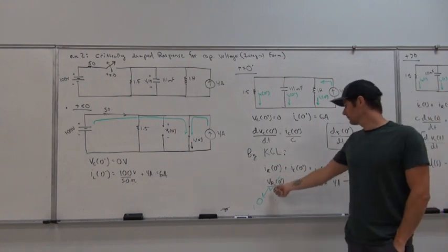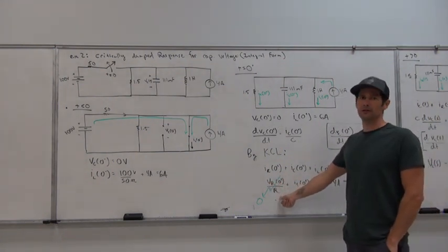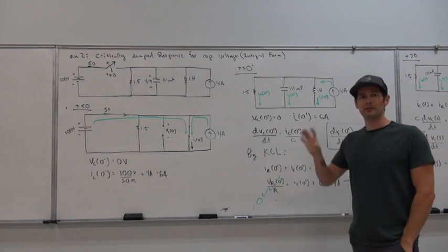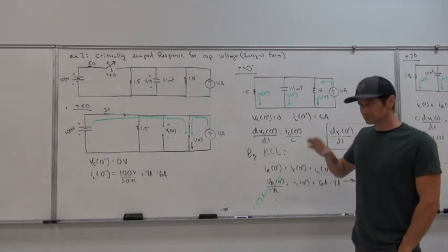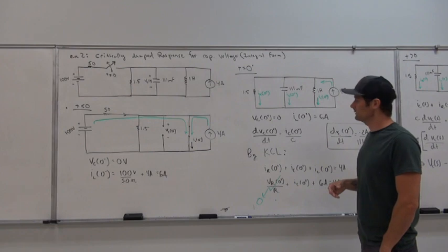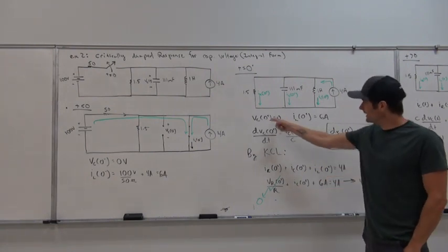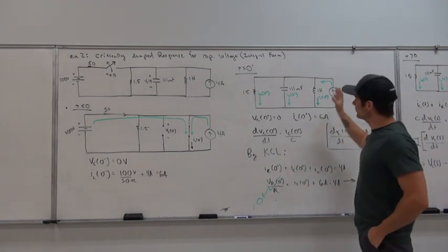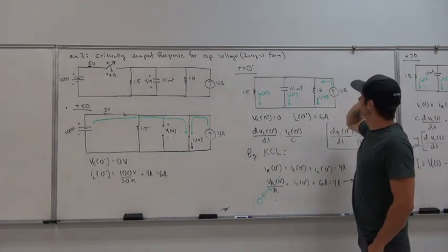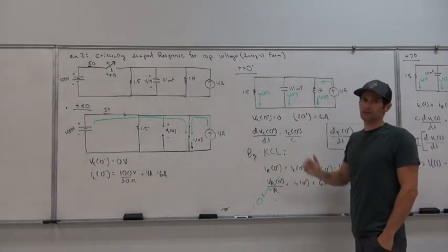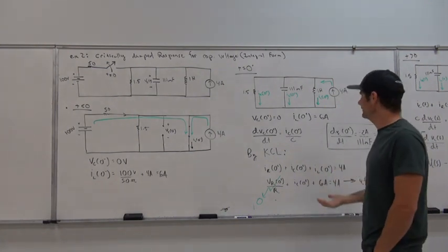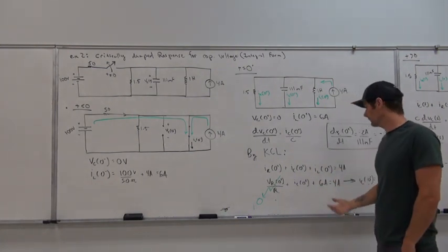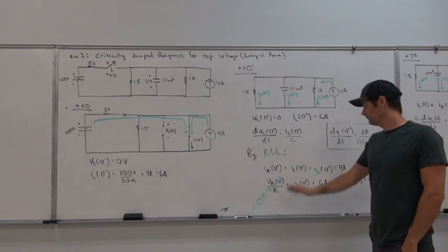But IR of 0 plus, that's VR of 0 plus divided by R. Well, that resistor's voltage is going to be held to basically be 0, because the capacitor cannot instantaneously change its voltage. And so it's driving the value of the inductor as well as the resistor to have a value of 0 volts across it. So there you go. Bam, that was gone.